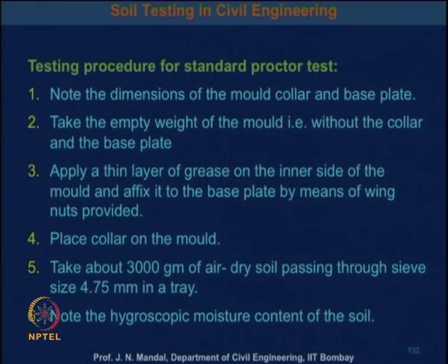So, the testing procedure for the standard Proctor test. Note the dimensions of the mold, collar, and the base plate. Take the empty weight of the mold, that is without the collar and the base plate.